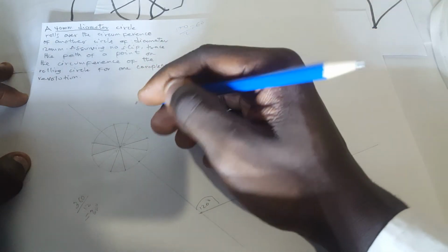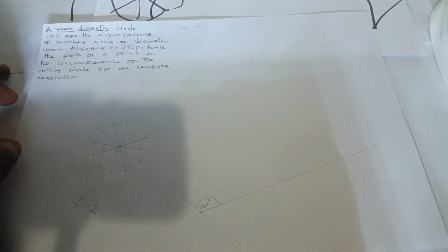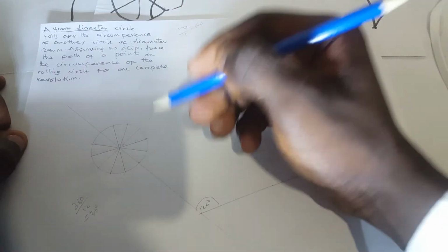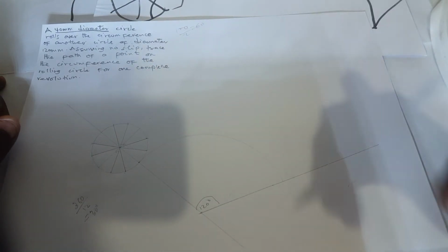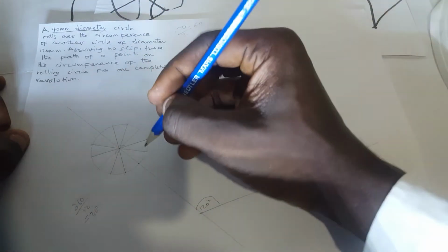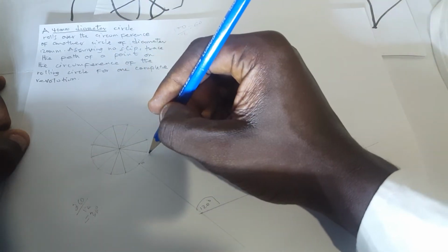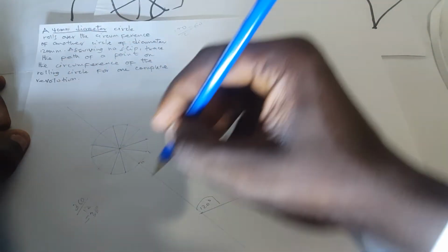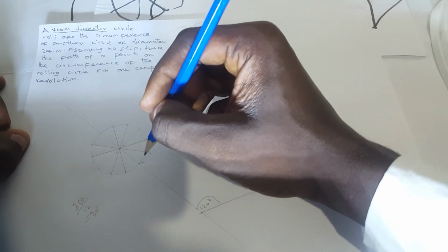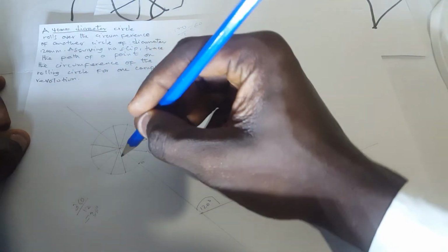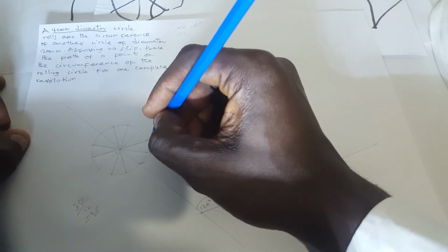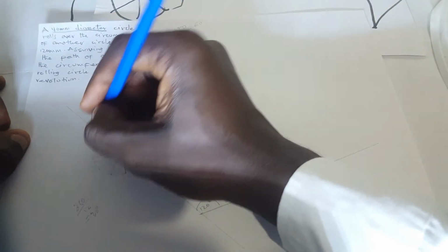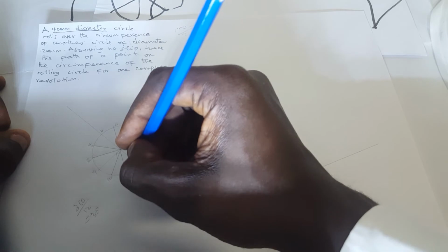what we have. Okay, now it doesn't matter whether you label it in the anti-clockwise direction or in the clockwise direction, but most important is that you start from the bottom for the epicycloid. But if it is the hypocycloid, you have to rather start from the top. So we start here with 0. You can choose to go like this 1, or you can write the 1 this way. They go in the clockwise direction, but I rather want to go in the anti-clockwise. So 1, 2, 3, 4, 5, 6, 7, 8, 9, 10, 11.